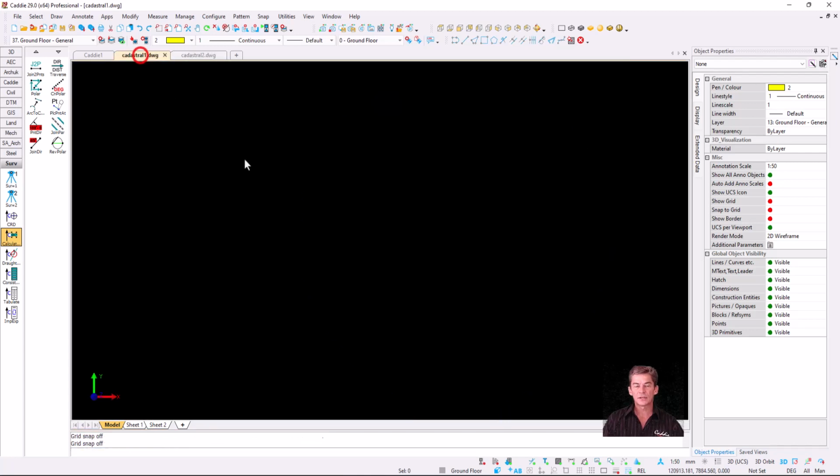The next command is traverse related, so we remain under the Calculations option. We're going to click on the command that says Traverse and Adjust. CAD will ask us to indicate the start of the traverse. I'm going to go freehand. CAD asks us the distance. I'm going to say 50 meters, and I press enter. CAD asks us the direction.